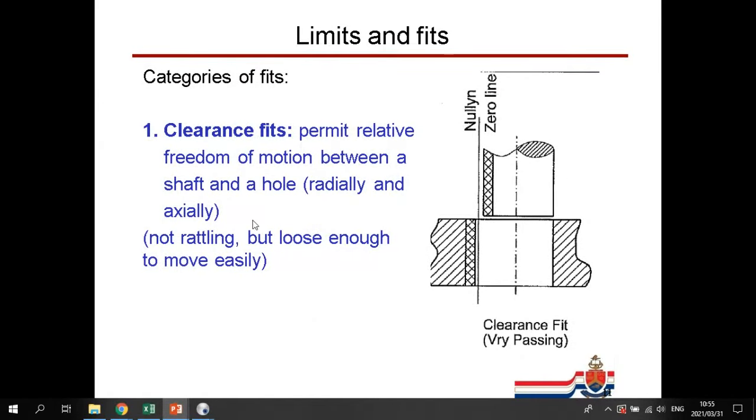So we have different fit categories. The first one is a clearance fit. That basically says the variation in the holes will be such that even the smallest hole will be bigger than the biggest possible shaft. So that's a clearance fit, meaning no rattling, but loose enough to move easily. It's not so loose that it will just fall out, but it can slide the one in the other one.